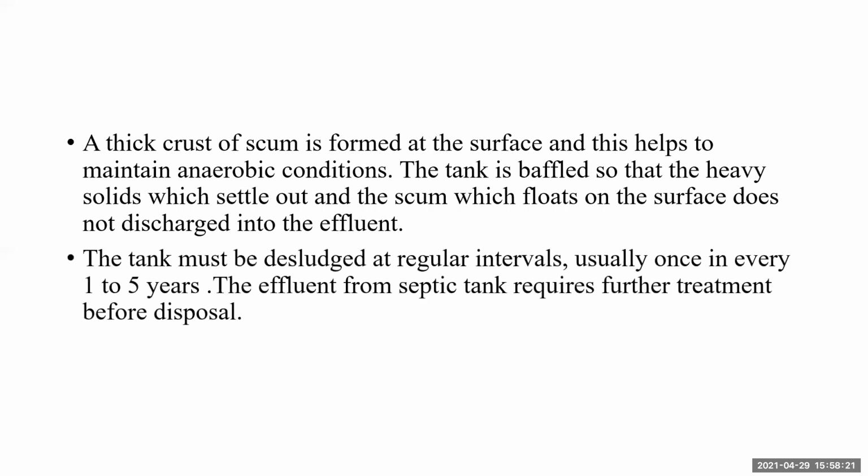And desludging: because the solids settle at the bottom of the tank and undergo digestion by anaerobic bacteria, the tank has to be desludged. The sludge that settles at the bottom of the septic tank needs to be removed at regular intervals, once in every 1 to 5 years. The effluent from the septic tank requires further treatment before disposal because it contains pathogenic microorganisms.